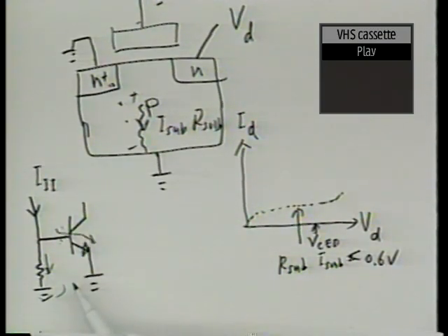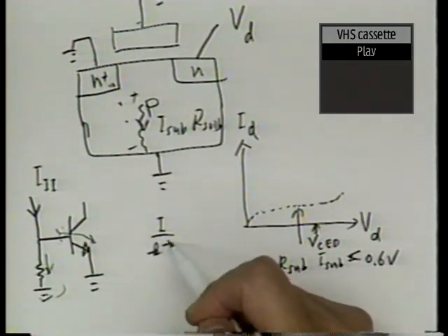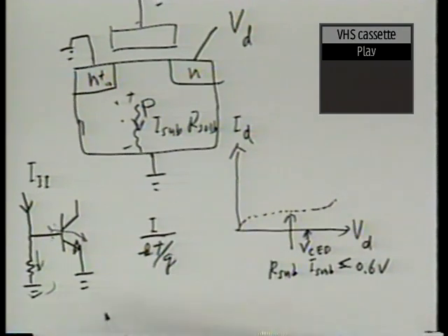that junction. But do you remember that the impedance of a forward biased junction drops precipitously, exponentially with increasing forward bias? Remember the G of the diode? What is the impedance of a diode? Actually, it's equal to I divided by kT over q. This is admittance, I'm sorry. Admittance equals I divided by kT over q. So when I is large, this becomes large.